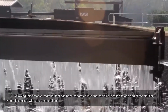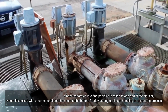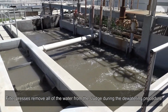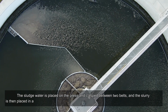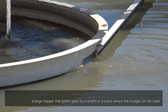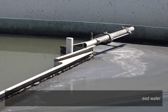Following this process, material that has been separated into fine particles is raked to one end of the clarifier, where it is mixed with other material and then sent to the bottom for dewatering or sludge handling in a separate process. Filter presses remove all of the water from the sludge during the dewatering procedure. The sludge water is placed on the press and clasped between 2 belts, and the slurry is then placed in a large hopper that either goes to a landfill or a place where the sludge can be used. As a general rule, this process's wastewater is recycled into the clarifier's feed water.